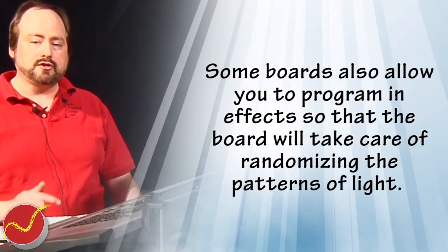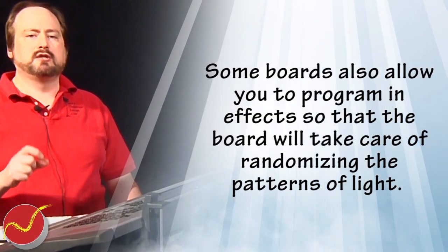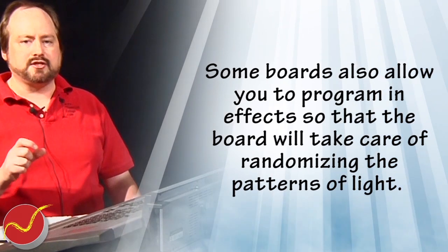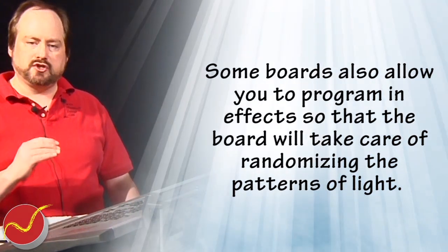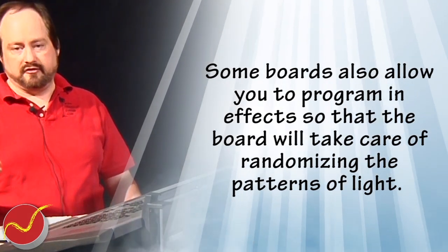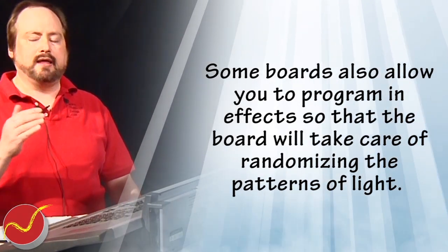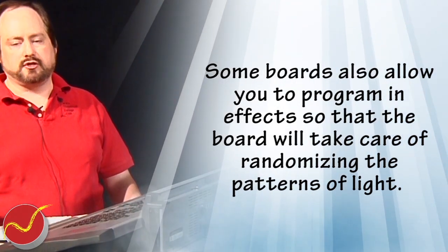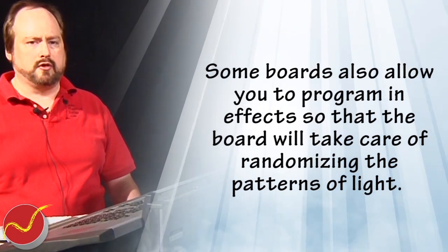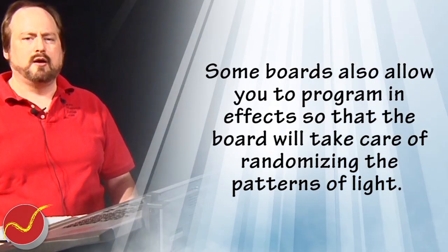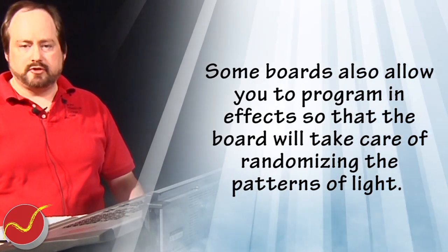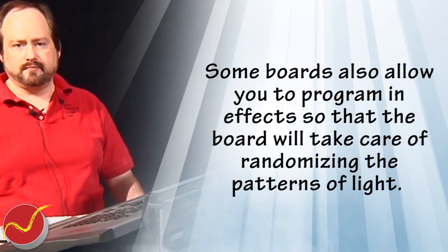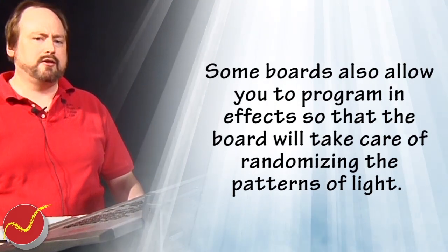Some boards also allow you to program in effects so that the board will take care of randomizing the patterns of light. They typically work by having you set which channels should be involved in the effect and what the high and low settings for those effects should be. The programming for those types of things vary greatly by every light board I've come across, and some of them don't have those functions built in. So it's best for you to check the manual of your particular light board.